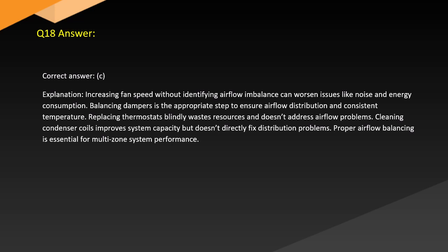Answer. Correct answer: C. Explanation. Increasing fan speed without identifying airflow imbalance can worsen issues like noise and energy consumption. Balancing dampers is the appropriate step to ensure airflow distribution and consistent temperature.